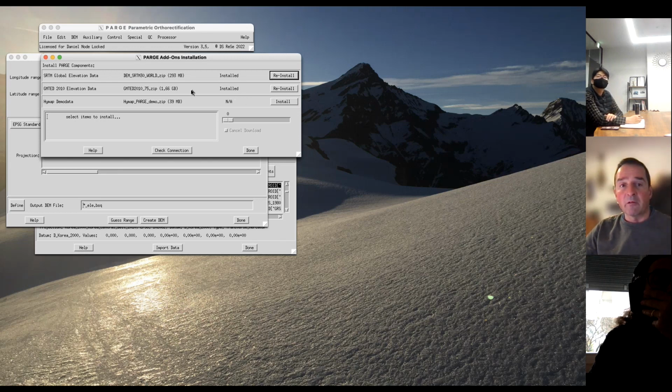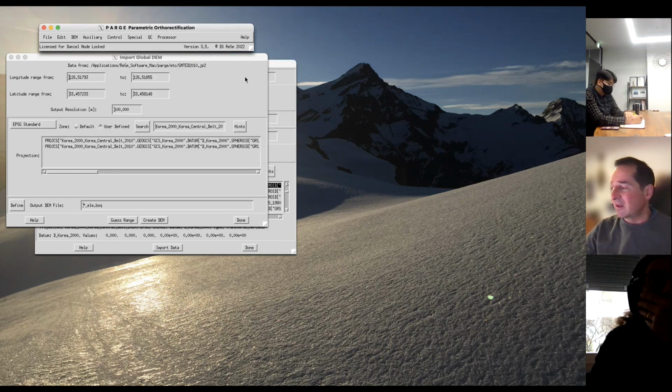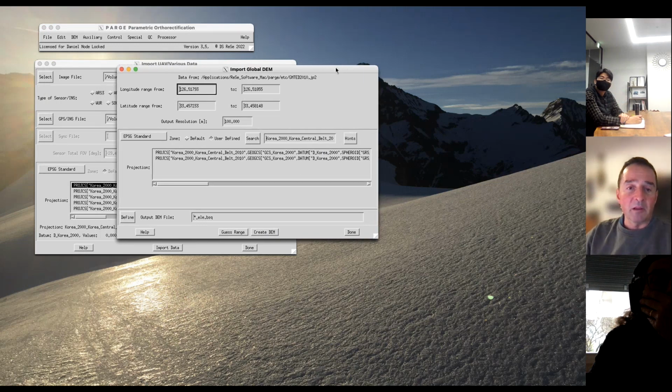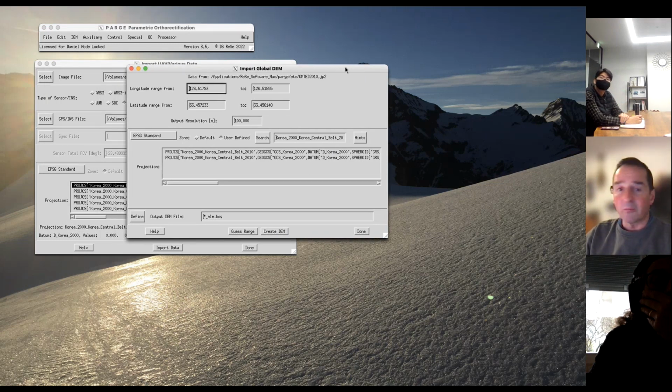It's a very rough elevation model, 100-meter resolution, but it gives you an idea of the ground altitude. You would need to install it through the help menu if you haven't done that yet. It will be downloaded directly. Or you could provide your own DTM, of course, from your mapping agency or wherever you got it from.